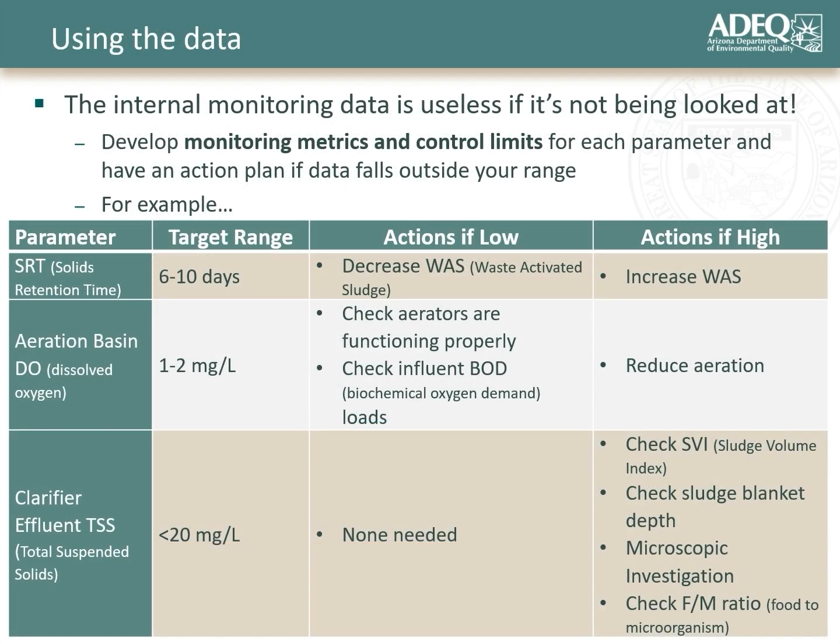Besides monitoring your effluent to make sure that you meet your discharge limits, it's important to monitor different points inside your wastewater treatment plant to ensure that each unit operation is performing as it should. And then, if it's not, making appropriate changes as needed. That way, you can help prevent a future downstream effluent exceedance. So, being mindful of your system operations and making a plan to adjust as needed is really important for your system. So, let me give you a few examples of things we'd recommend.